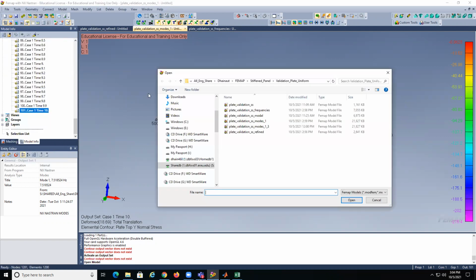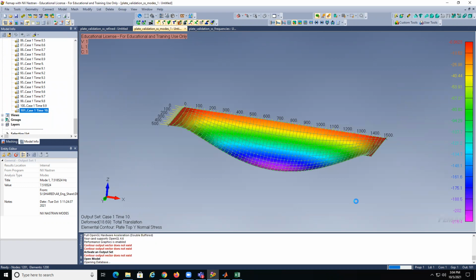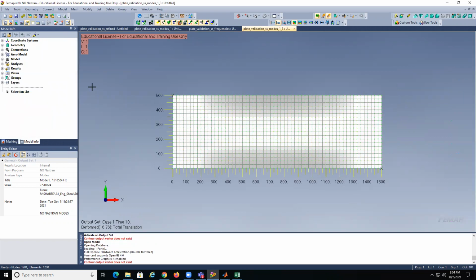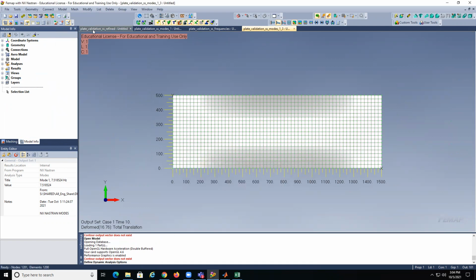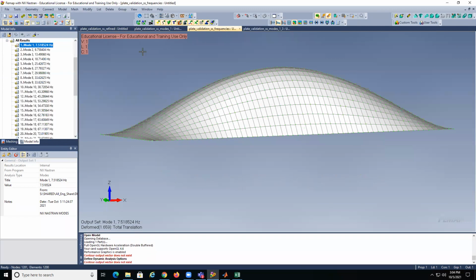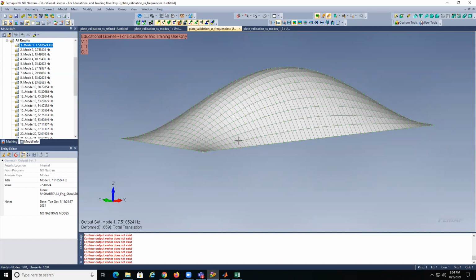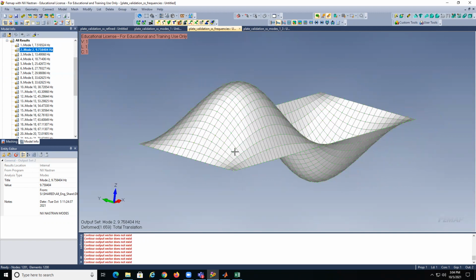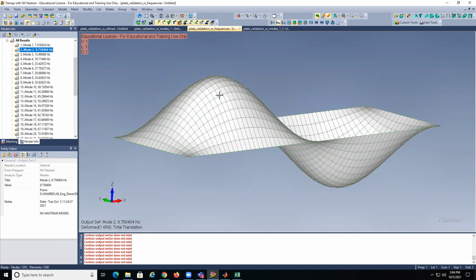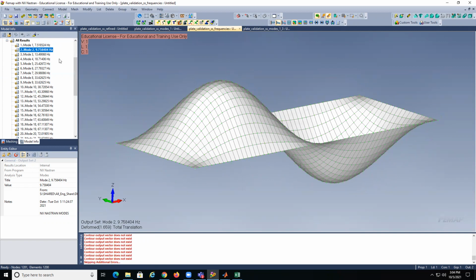So if I open, this one is already set up. So this time which mode will we be using? Let's see on the analysis which one I'm using. So model, load, dynamic analysis, it says I'm using 3. But if I'm using 3 modes, what would be those 3 modes? Mode 1,1, mode 2,1, that actually will have no contribution because it's symmetric. I will explain now why it's 0. So 1,1, 2,1,